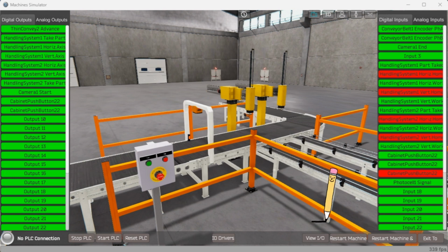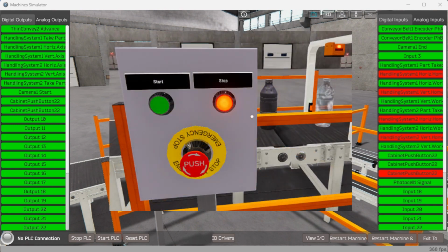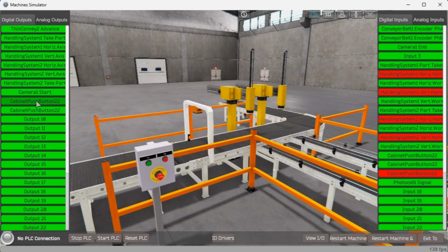This does not have to be a formal document. You must have a method to account for every condition in the machine being programmed. Our machine has a control panel with lighted push buttons. If the machine is stopped and ready to be started, the start push button light will flash. If the machine is running, the red light will be on. If both lights are off, the emergency stop has been pressed. The packaging sorting line is reset if the stop button is pressed within 0.8 seconds twice.